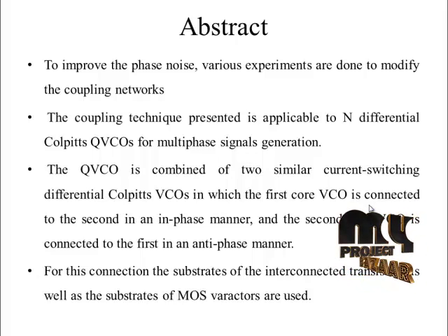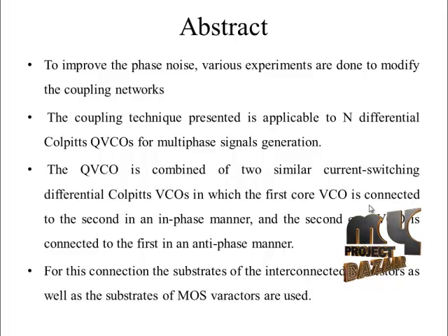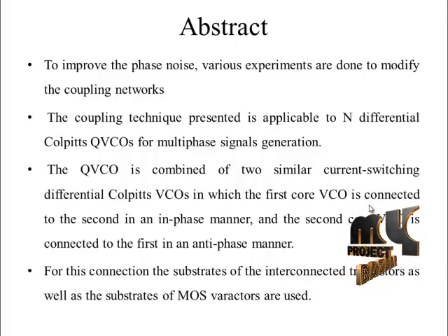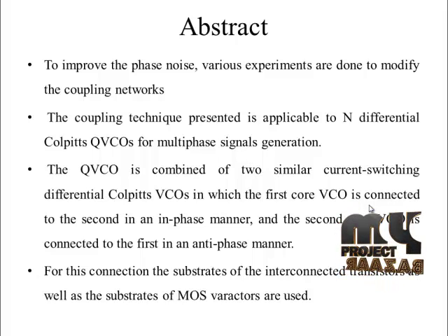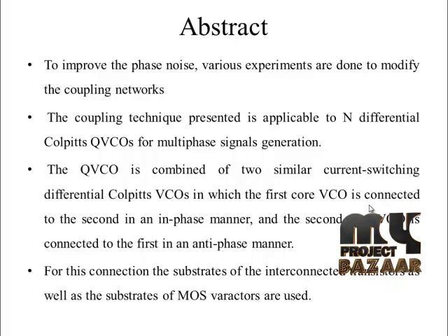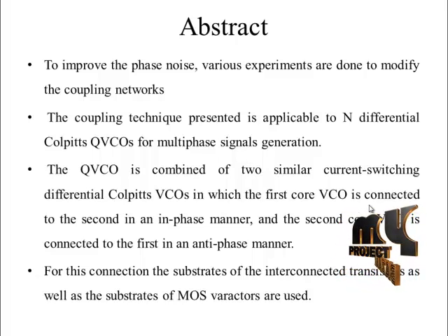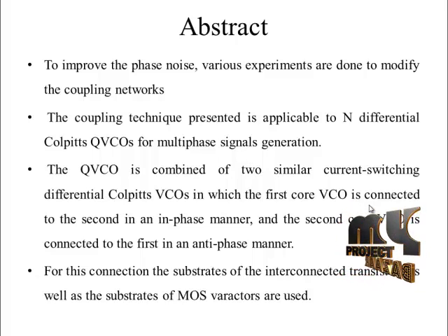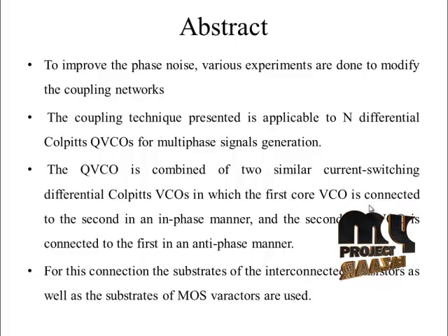to the substrate of cross-connected transistors as well as the substrates of MOS varactors, which alleviates the need for any extra elements for the coupling, which could add noise and increase power dissipation. A linear analysis is presented that confirms that the proposed circuit generates quadrature waveforms. The proposed coupling technique can be generalized to n differential Colpitts VCOs for multiphase signal generation.